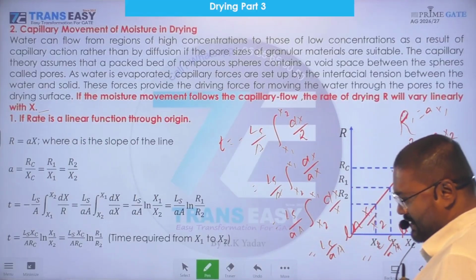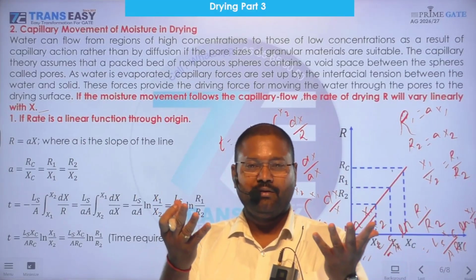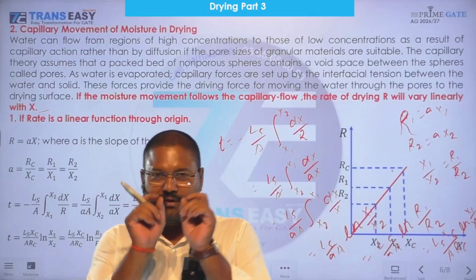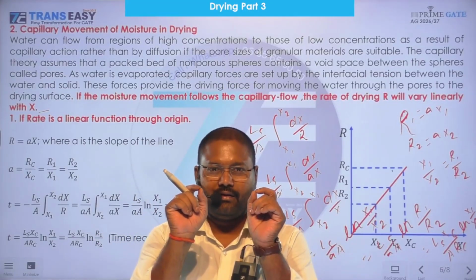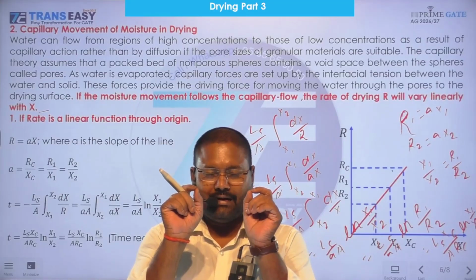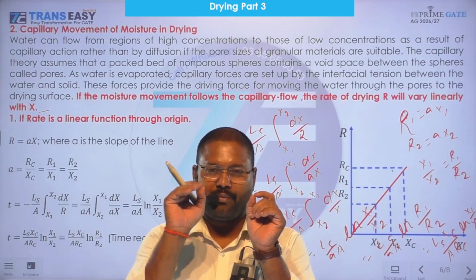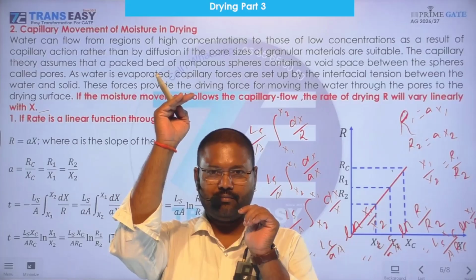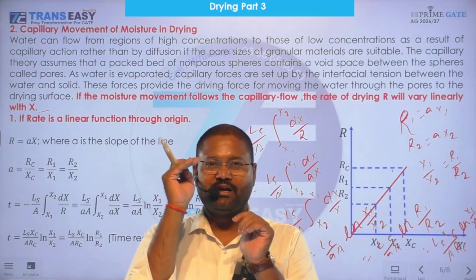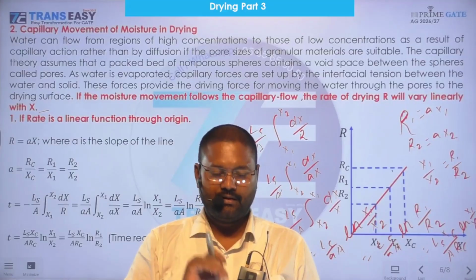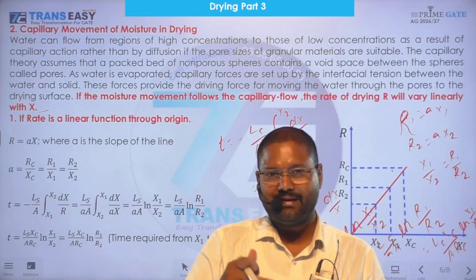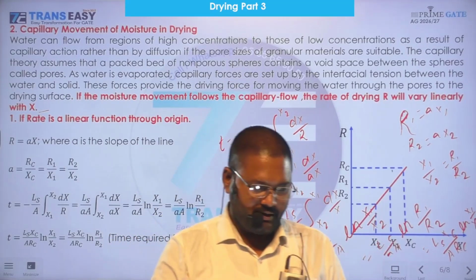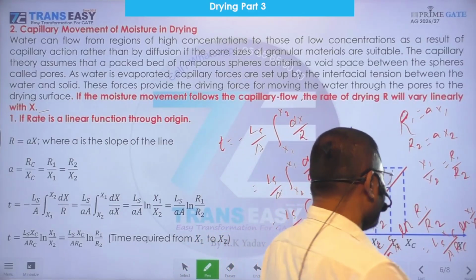Porous has interconnecting pores, and between grains we have interconnecting pores. So interfacial forces acting between surface of grains and water continuously on the surface. Drying gas is evaporating liquid, so concentration on the top is lower, concentration at the surface of material under drying is lower than concentration inside the material. So this difference causes flow of liquid from interior to surface by capillary action.